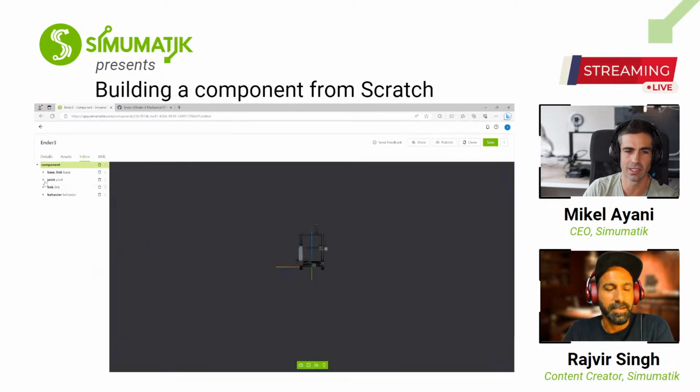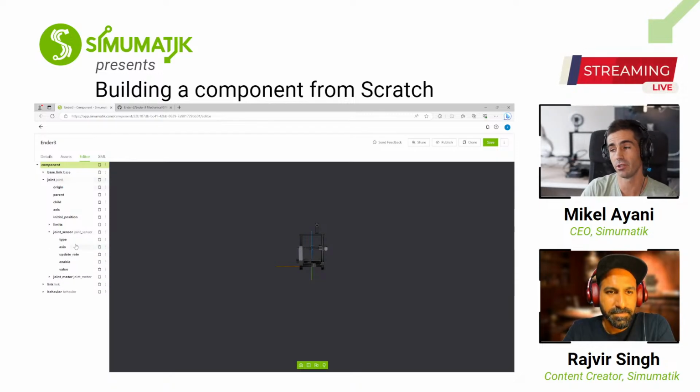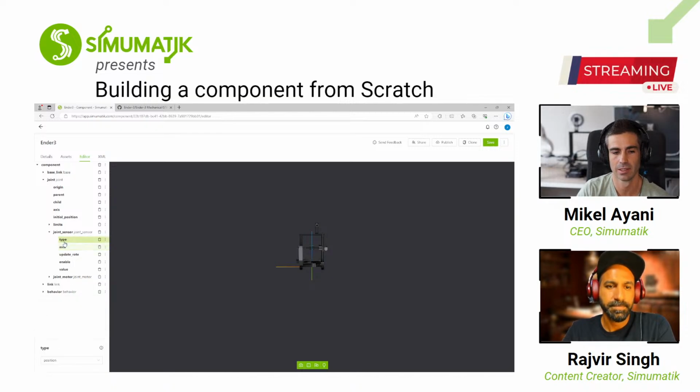Just to show more features of joints, we can add what is called a joint sensor. Basically, because a joint can have more than 1 degree of freedom, we could add more than 1 degree of freedom if we would like to move it in the x-axis or whatever. You need to tell both the motor and the sensor which axis they will be measuring or acting on. So here we need to say we want to sense the Z axis. We want to sense the position at the rate 0.1, which is good. Let's enable it. It's true.